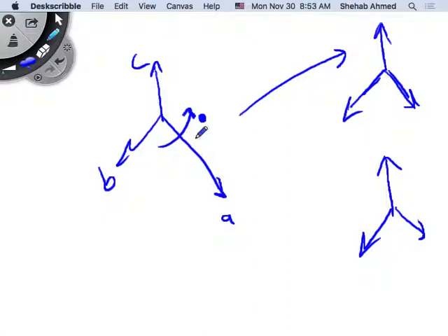So let's say we will call this positive sequence. So an observer will stand here, will see phase A, phase B, and phase C. Same thing, if you're measuring, you will see phase A first, then phase B, and phase C. That's positive sequence. So what symmetrical components theory tells me is that I can take this unbalanced system and chop it up into a positive sequence circuit, a positive sequence supply, meaning this is A, this is B, and this is C, rotating this way for an observer standing here.